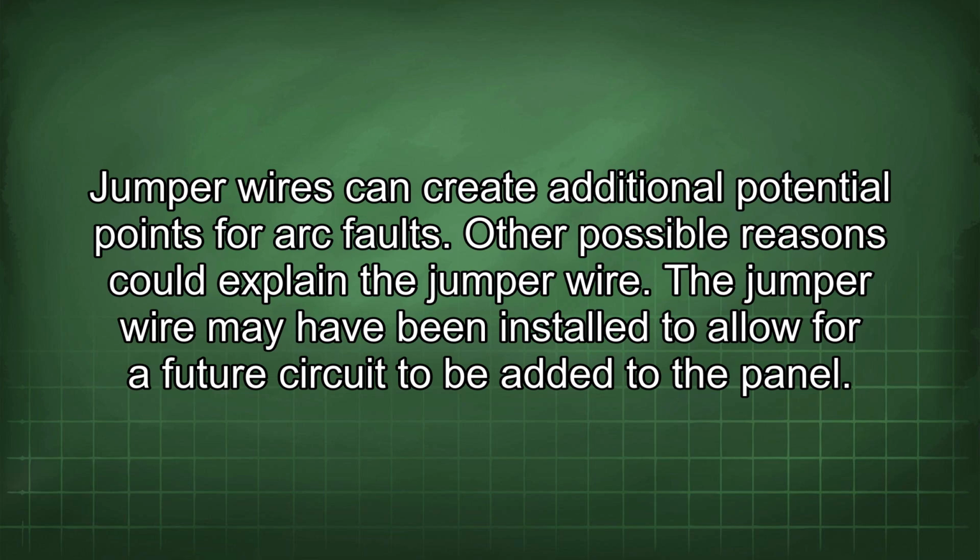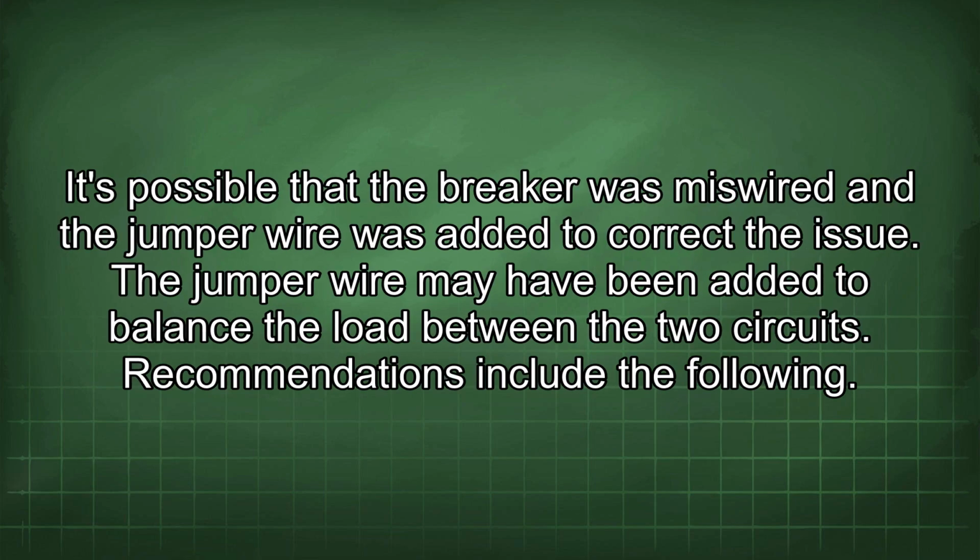Other possible reasons could explain the jumper wire. The jumper wire may have been installed to allow for a future circuit to be added to the panel. It's possible that the breaker was miswired and the jumper wire was added to correct the issue. The jumper wire may have been added to balance the load between the two circuits.